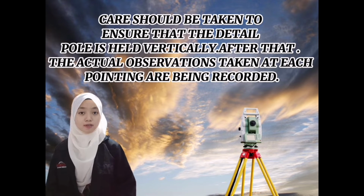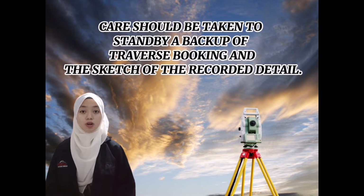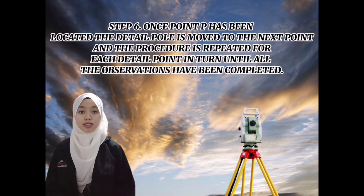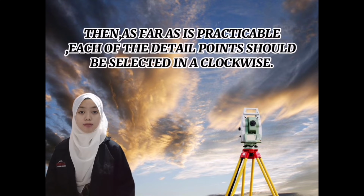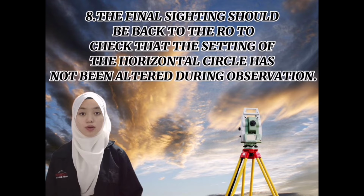After that, the actual observations taken at each pointing are recorded. Care should be taken to keep a backup of the traverse booking and a sketch of the recorded detail. Step 6. Once point P has been located, the detail pole is moved to the next point and the procedure is repeated for each detail point in turn until all the observations have been completed. As far as practicable, each of the detail points should be selected in a clockwise direction. The final setting should be back to the RO to check that the setting of the horizontal circle has not been altered during the observation.